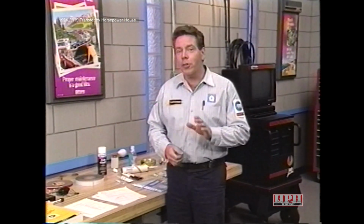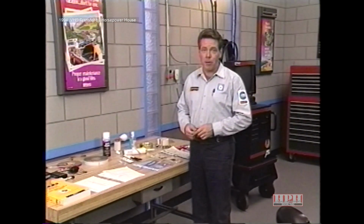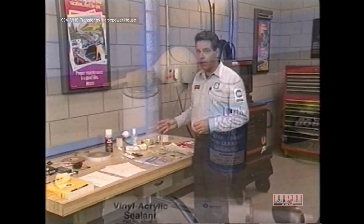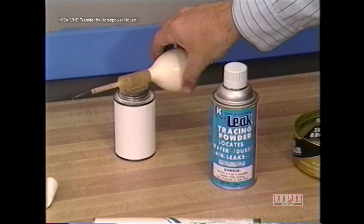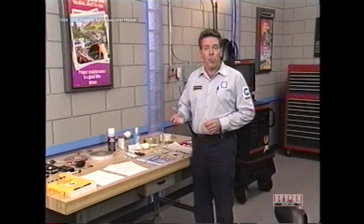After trying one or all of the methods we've described, if you still can't find the problem, don't get discouraged. There are still a few more methods you can try that may reveal leaks too small to be detected by the others. One method, the tracing powder test, uses tracing powder, leak detection powder, or a bulb syringe filled with baby or talc powder to help detect small leaks in vent and convertible window seals and door seals.